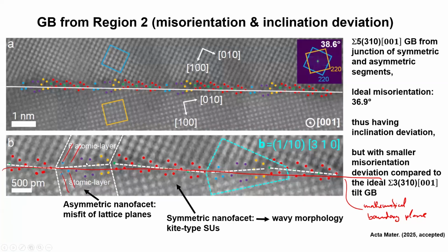How do you call these defects if you have an incommensurate region? It's a dislocation. You like dislocations in the boundaries. This is actually a dislocation. I like it, but when we see it in TEM, a dislocation is a number of points that are not matched. If I see only lattice fringes, that's why I got that. Yeah, here you have a number of atoms because each lattice point here is 100 or 1,000 atoms long, right? Because we just see the projected 2D image of a 3D structure in TEM. That's always the difficulty.